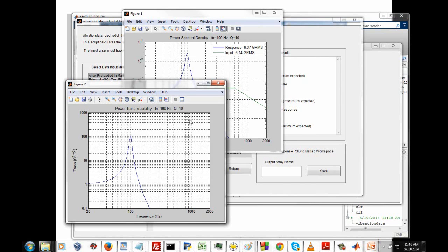That's why we like to use the half power bandwidth method as an alternative for determining what the Q value is, as if we had measured data. In this case, we already know what the Q value is because this is all an analysis, but imagine that this were measured data. Then we should use the half-power bandwidth method.